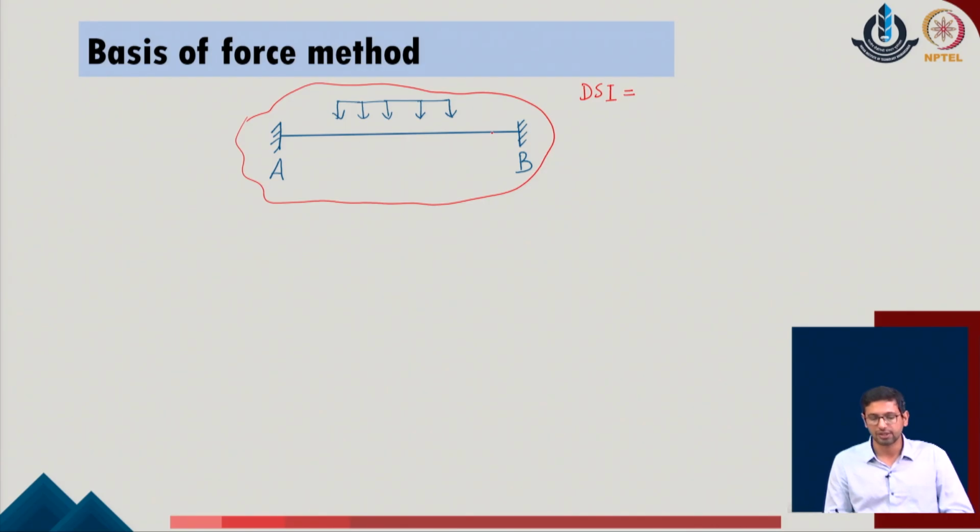If we consider that the axial deformations are negligible, they are not included. So, at both the ends we have two reactions, one translational and the second a moment reaction. With respect to these four unknowns in the given problem, we have only two equilibrium equations, which are the summation of the forces along y and the summation of the moments about the z axis being 0, and that brings us to say that the degree of static indeterminacy in the problem is 2.